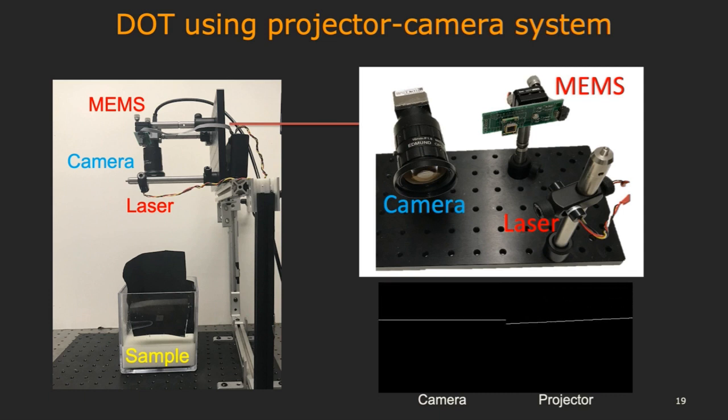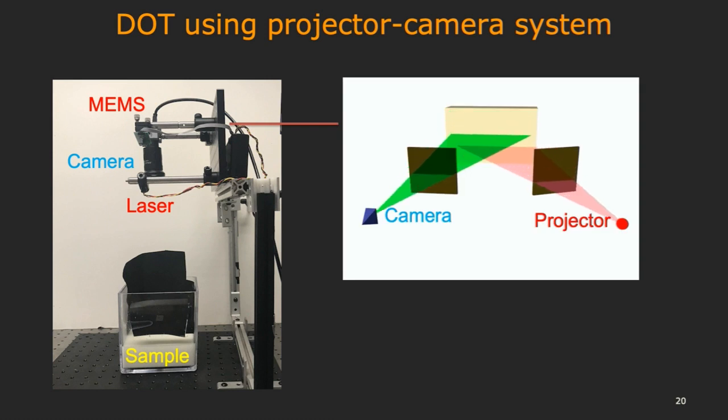During imaging, we can synchronize the camera and projector such that when one epipolar line or one row on the camera is exposed, the corresponding epipolar line on the projector image plane is illuminated. To capture a short-range indirect light image, we add a constant delay between the exposed row and the corresponding epipolar line on the projector image. This results in two synchronized scanning planes.